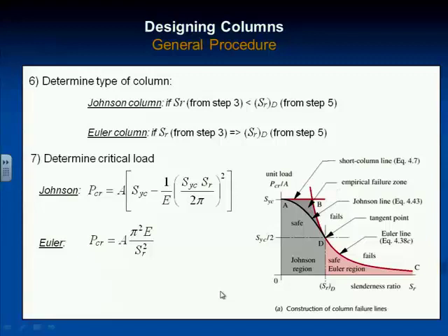Let me say a word about safety factor. Every time I bring it up, I want to reinforce the idea. It's an indication of your uncertainty. If I knew perfectly well what my material strength was, I knew exactly what my loads were, I could afford to have a very small safety factor, because I'm pretty confident of my numbers. But most of the time I have neither of those things known very well. For one thing, I may assume one load and the user doubles it.